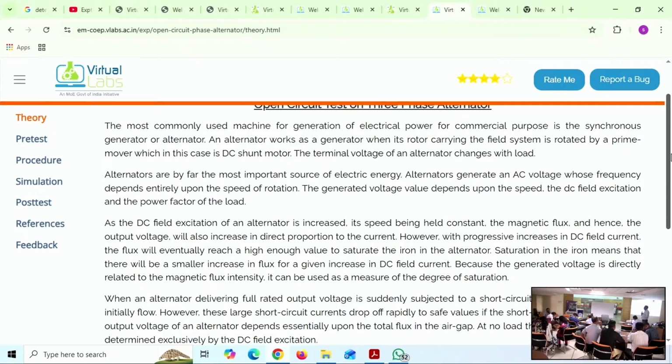One more thing, finding the resistance of the armature winding. Resistance of the armature winding is simply V by I, Ohm's law. Nowadays students get true RMS measuring multimeters. They take the 2 leads, put them in the range they are going to measure, simply connect, and get one reading.